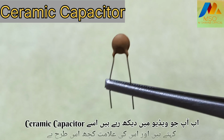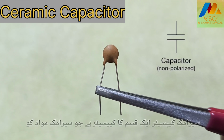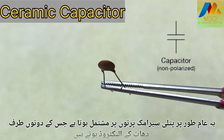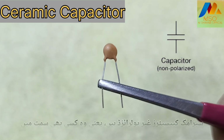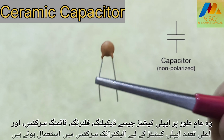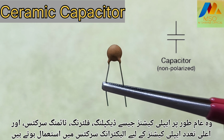Now what you see in the video is called a ceramic capacitor and its symbol is something like this. A ceramic capacitor is a type of capacitor that uses ceramic material as the dielectric. It typically consists of thin ceramic layers with metal electrodes on either side. Ceramic capacitors are non-polarized, meaning they can be connected in any orientation. They are commonly used in electronic circuits for applications such as decoupling, filtering, timing circuits, and high-frequency applications.